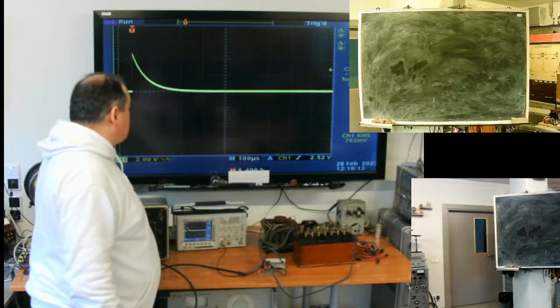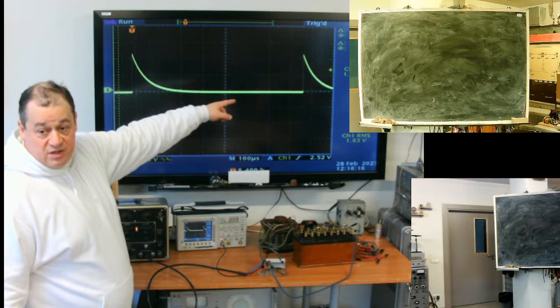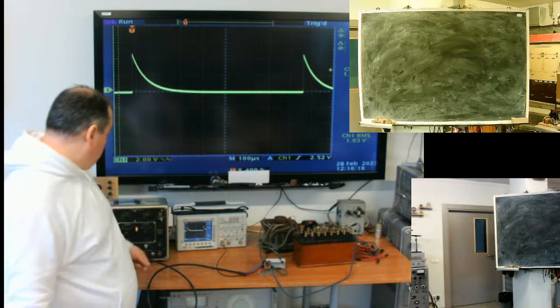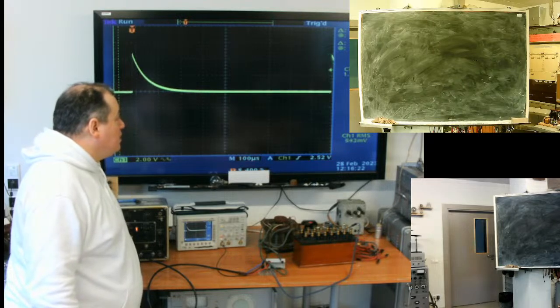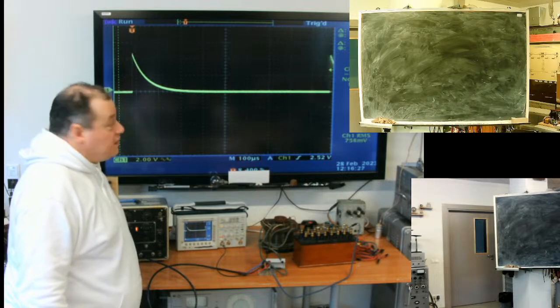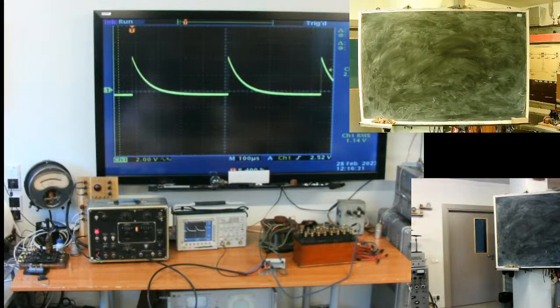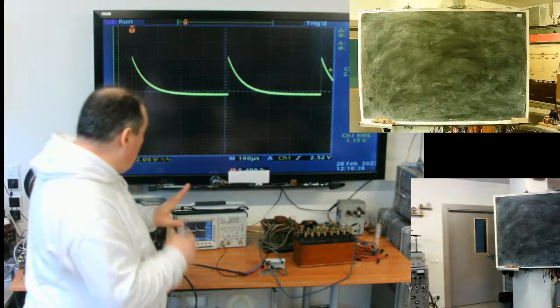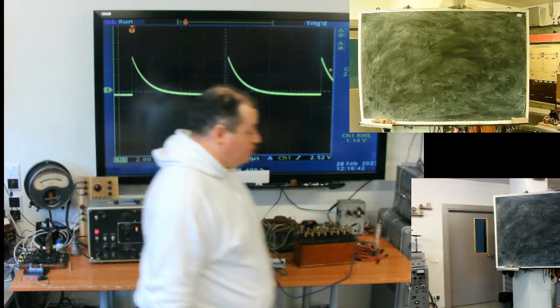If the next one comes in, now for the scope it's periodic. It can calculate frequency and period, no problem. Non-periodic. Still periodic. When the next pulse from the sequence shifts outside of the time margins, outside of the observation window, for my scope the signal becomes non-periodic.